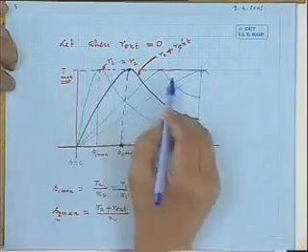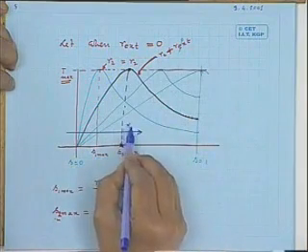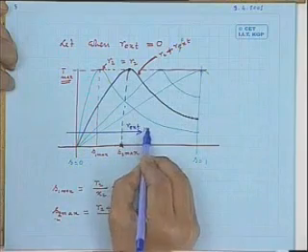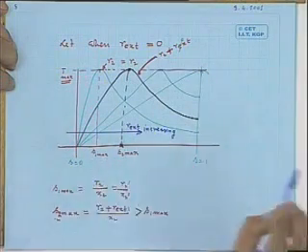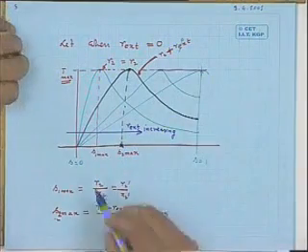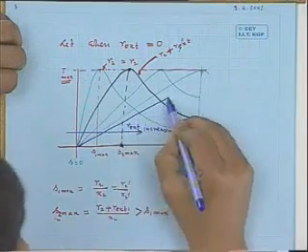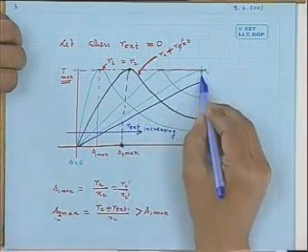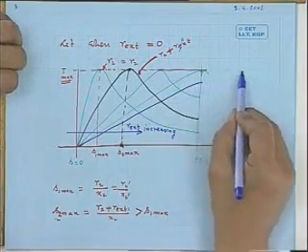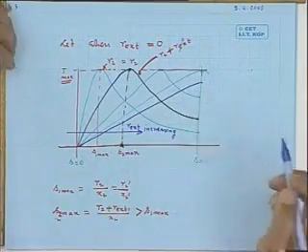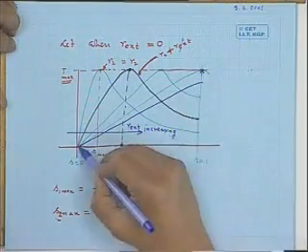So this curve from left to right, if I draw it, you remember this is R2 increasing, R external increasing. Of course, further increment in R2 dash will once again start reducing the value of the starting torque, because this point will lie somewhere here where the machine cannot operate.